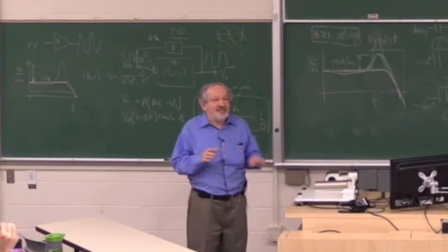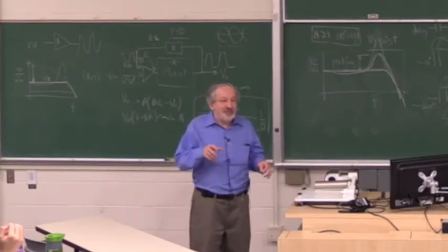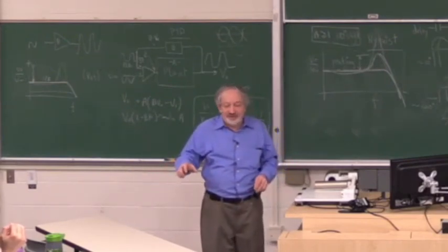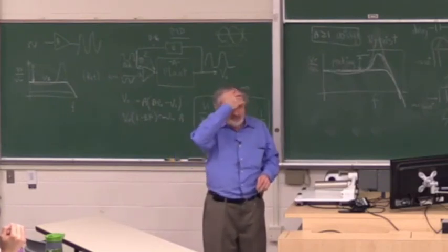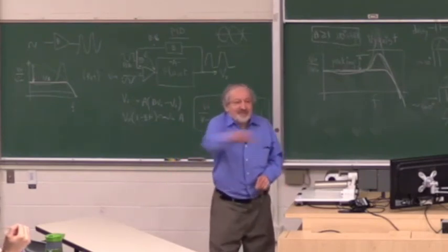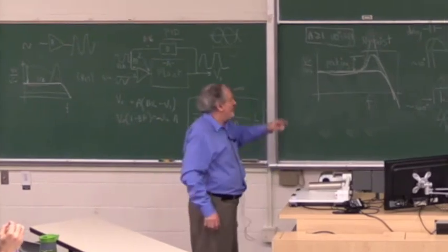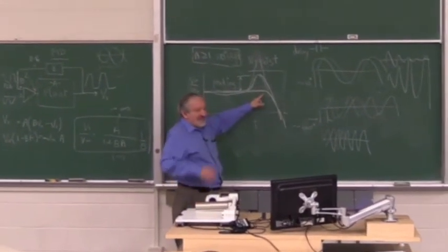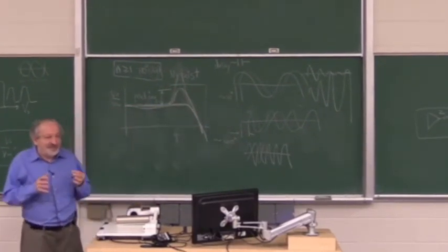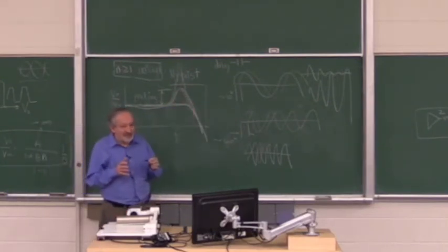This concept is true for any system: robotics, servo, telecom. Say you made a robot which moves an arm, and you want to make sure this robot wouldn't suddenly become unstable. So what you do is drive it with a sine wave. You tell the robot to do this, and then you go faster and faster, and you measure the amplitude as a function of speed, and you plot it. And if towards the end it gets like this, you know there is some instability, and there is kind of a fight between the gain dying out and the phase shift increasing, but it's dangerous.